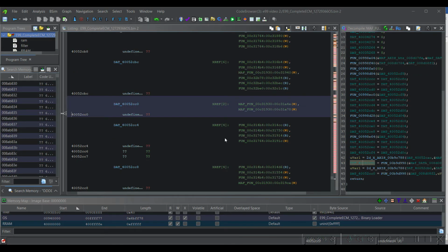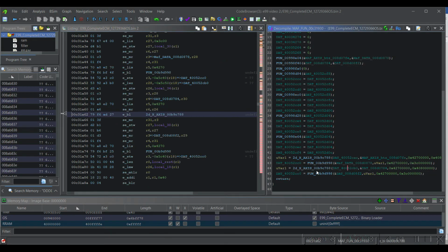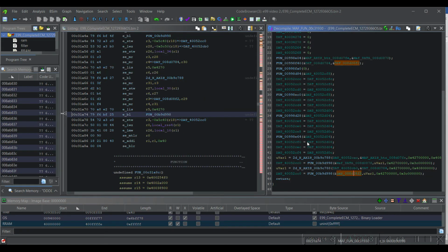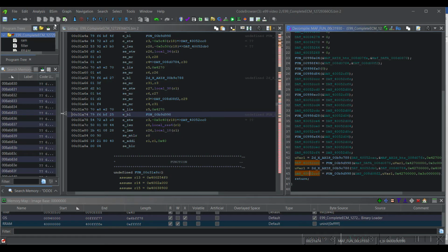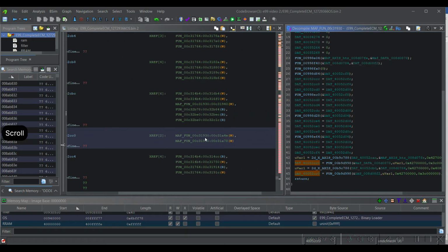All right, so we've completed analysis. There are a couple things that I want to check really quick. First, take note that we now have these two writes to 52CCO. This is a little weird to me. This looks like it's a second math table. It was suggested that some of these vehicles with E99 ECUs have two mass airflow sensors, so maybe it's mass airflow meter 1 and mass airflow meter 2, and both of them get written to this address. That could be. Also take note that there are no reads whatsoever from this address right here.